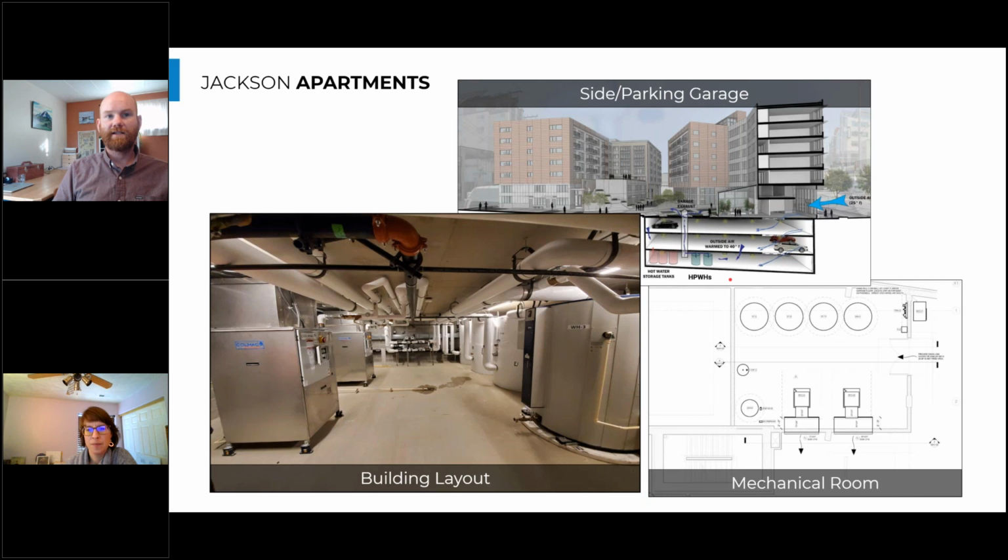Even if this garage has a lot of thermal mass, because of the number of hours these systems typically operate and the loads that they're serving, over the course of a week or even a day, you can actively cool that space if you're not discharging that air either towards the garage exhaust fan system that's pulling it out of the building or directly out of the building with ducting to the exterior.